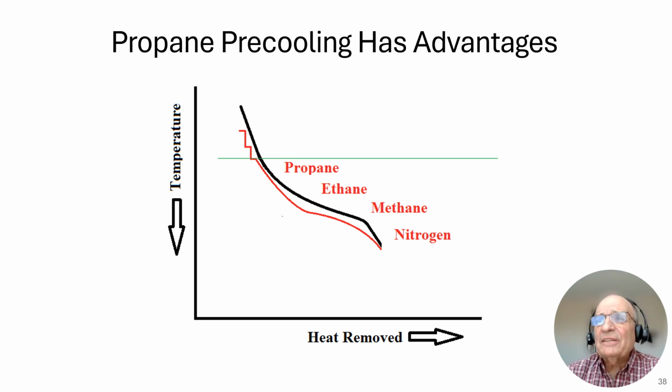And what's nice about this is with your feed gas always coming into your MR system at a fixed temperature, you don't have to deal with the swings of temperature during the day, where it's cold in the morning, warm midday, cold at night, and you're adjusting your MR composition to match your load on your chilling side.